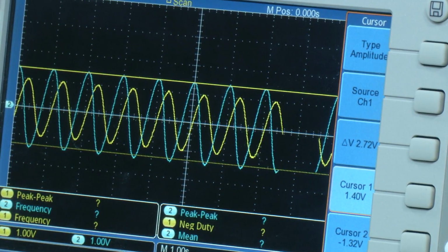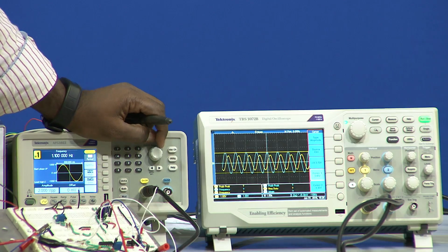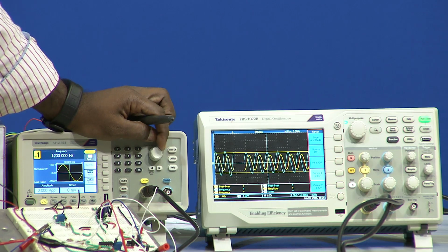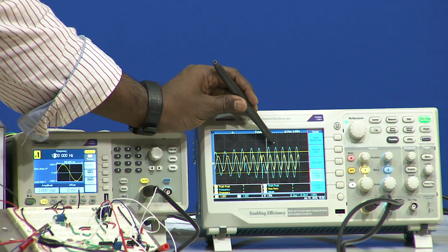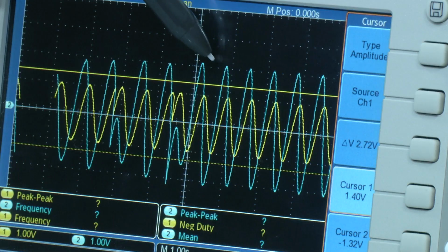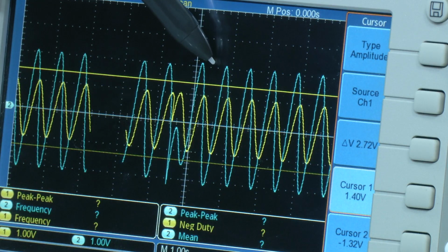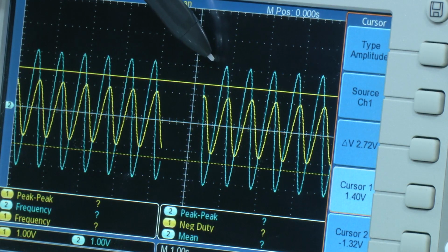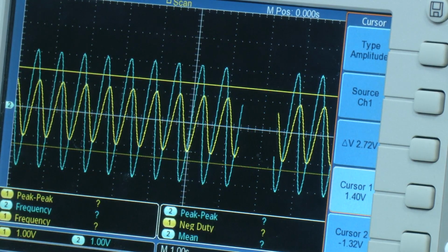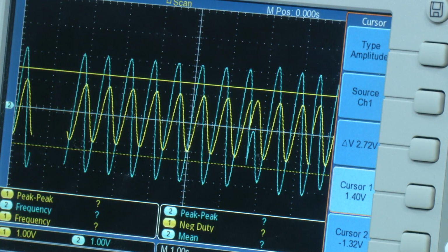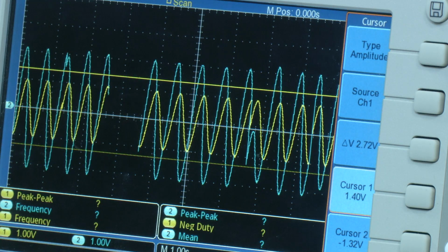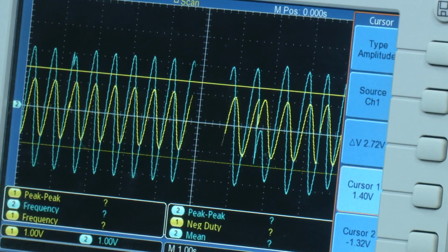So, it is very close to the cursor value. Now, I will slowly increase, let me see what will be the change. 1.4 hertz right now, 1.5. Now, when it is at 1.5 hertz, when you zoom into that, the gain is higher than 2. That is what we have observed in our simulation too. Increase 6, even higher, 7 higher, and 8 even higher.